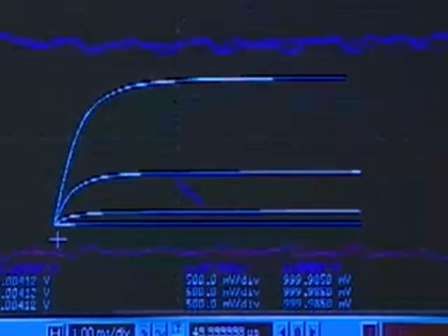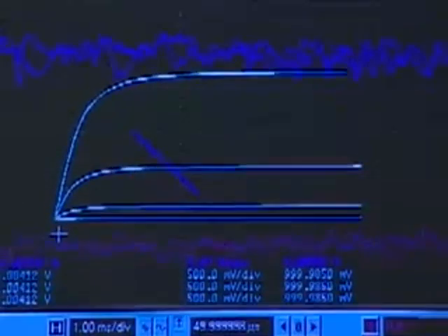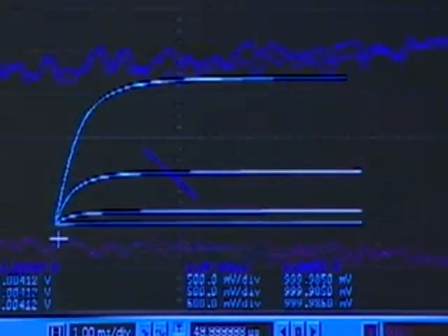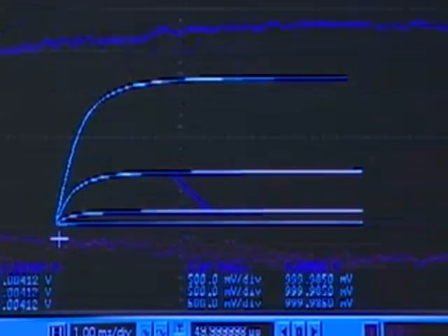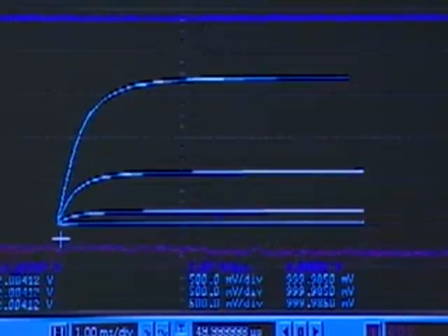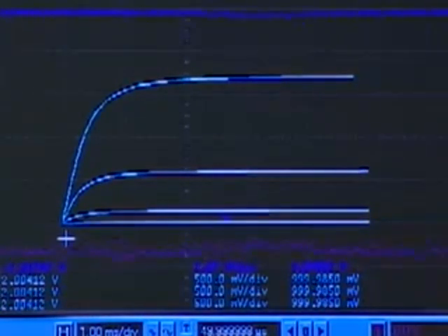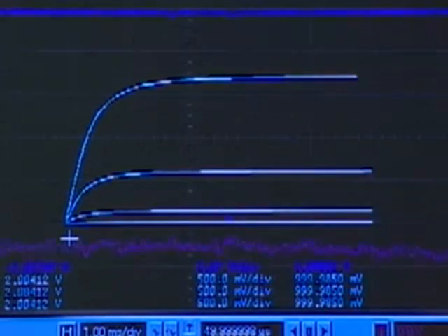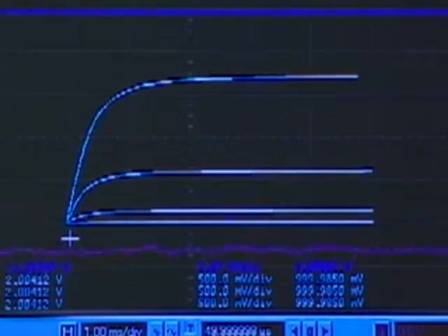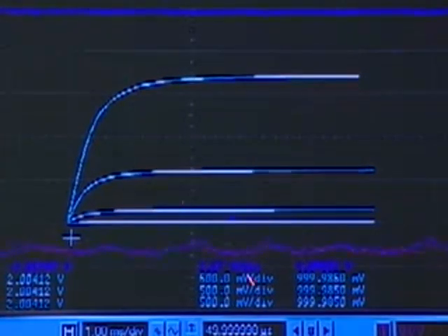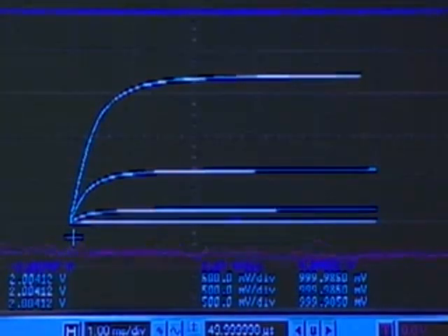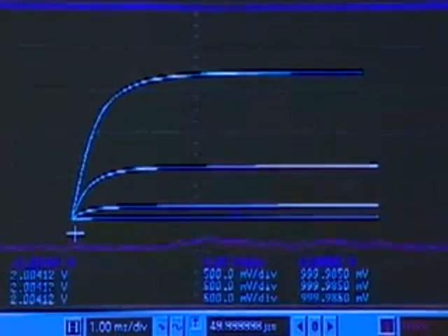So the volume increases, or rather the amplitude increases, by increasing the bias. Okay, now you should hear the volume go down and distortion. So notice now that the bias is way down here, so the gain is very low, and plus there is distortion because of cutoff. Now what I'll do is blast it up here, and you'll see that the volume has gone up, but then you'll see distortion again. And let's see if we can stand the volume here.